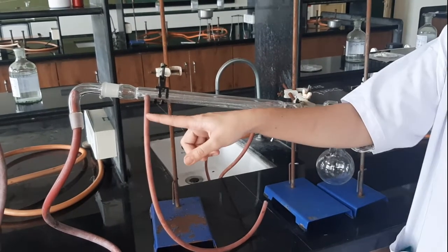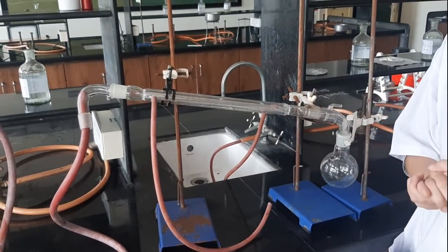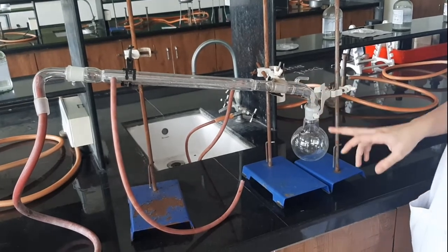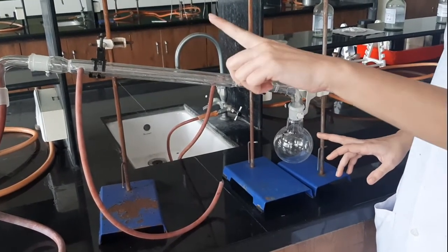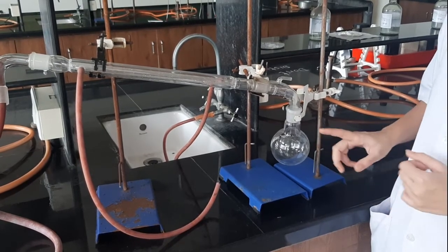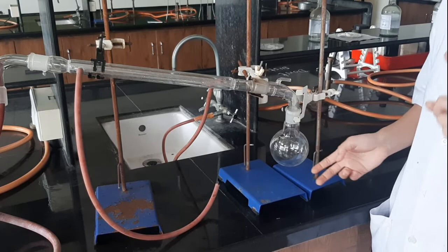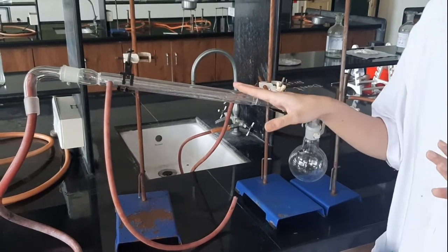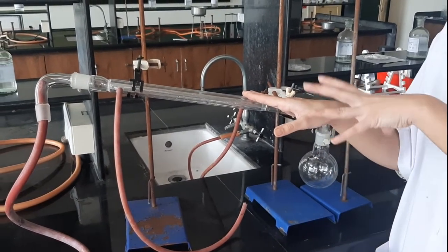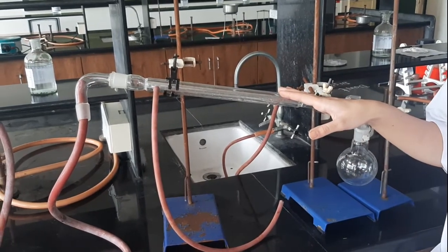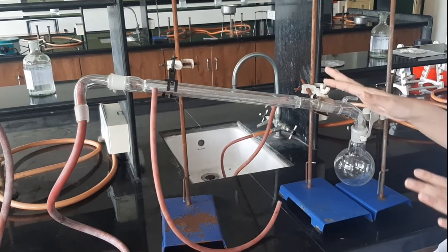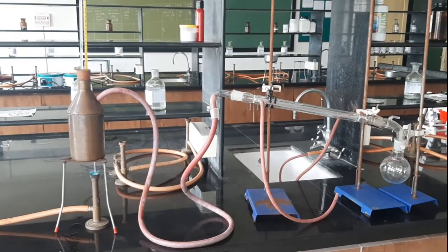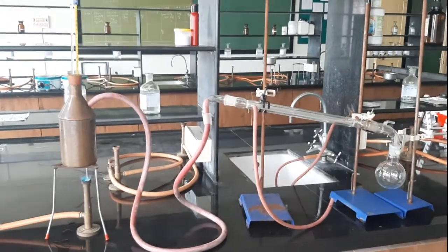Again we will start the steam generator and measure the temperature of the steam. When our steam gets condensed here and we get the first drop of the distillate, we will run this assembly for 5 minutes, and after that we will measure the volume and the temperature of this distillate, and the volume and temperature of the water which we have used for the cooling process. That water also we are going to collect and measure its volume and temperature. So this is the general setup and the process. Now we will proceed with the procedure. Now we have started the burner and we will wait till we get the steam.